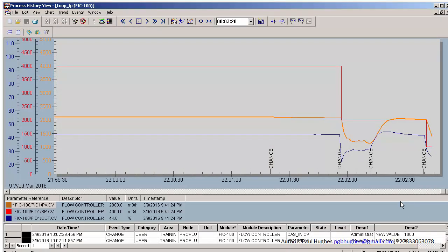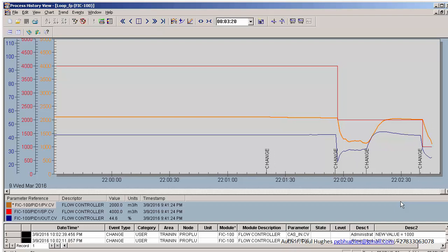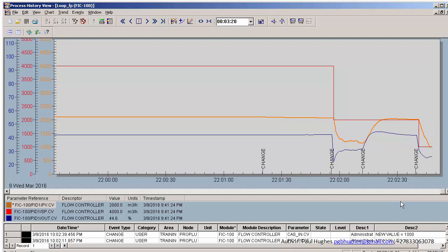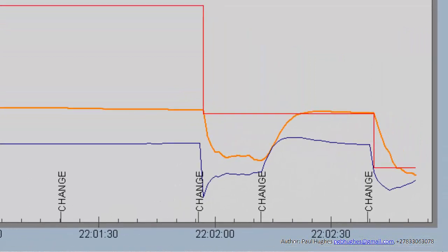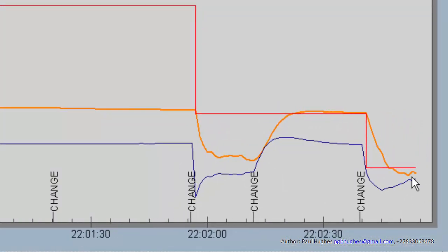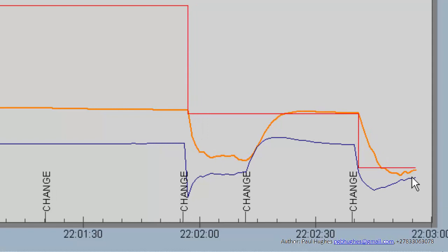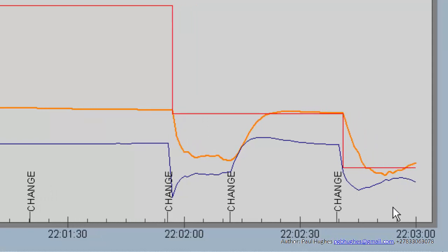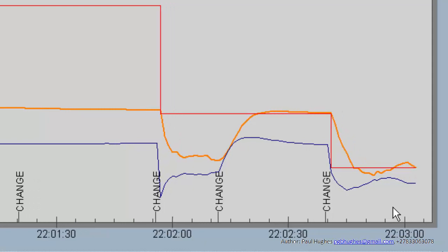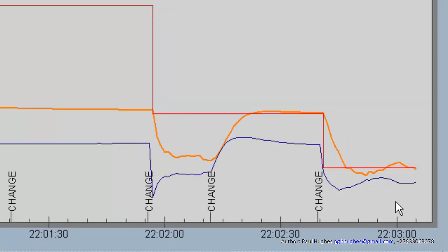Start to see the effects of the turn down problem. Should start to see a slightly noisier signal. You can start seeing the noise coming through. And there's some drift. A 1 second interval is probably not ideal now either.